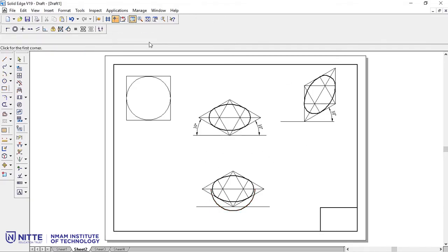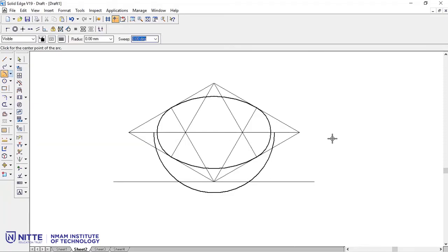Now if you see, while drawing the actual circle with actual radius, there are some gaps that are left out. Okay, so that needs to be filled out with either the freehand sketches, which you draw on the grid sheet. If not, here we are supposed to use arc by 3 points in order to manually connect this one.